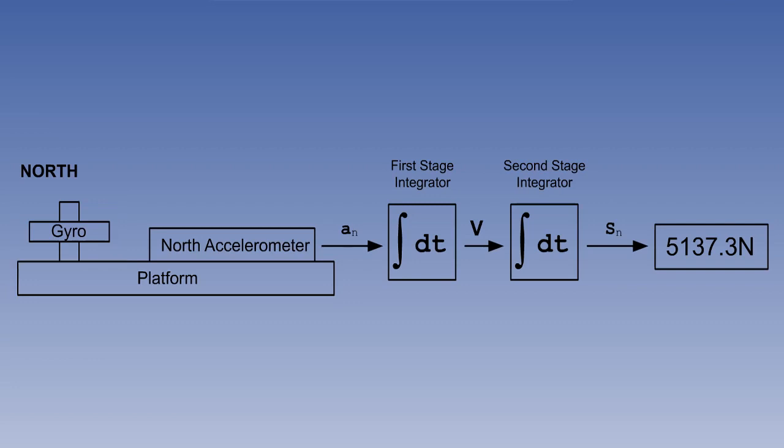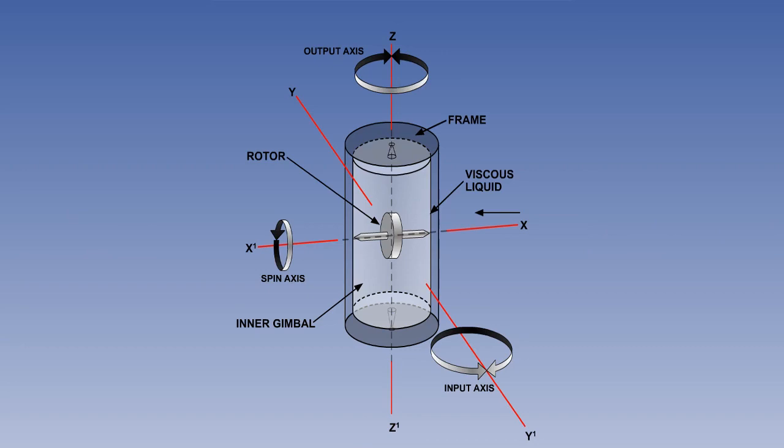The types of gyro used in INS can either be rate integrating gyros or 2 degree of freedom displacement gyros. Rate integrating gyros are widely used. The rate integrating gyroscope is a single degree of freedom gyro using viscous rather than spring restraint. However, the details of its construction need not concern us. We should simply note that, although mechanically it is a single degree of freedom system, because of the integration process, its output behaves as though it were a 2-degree of freedom system.